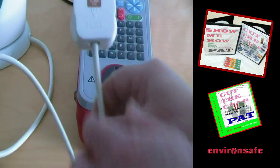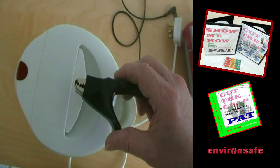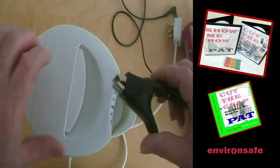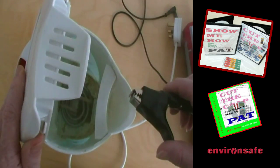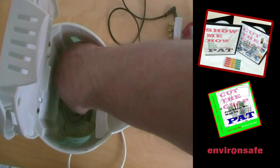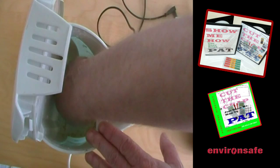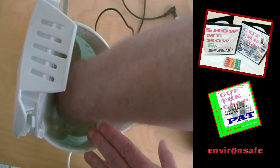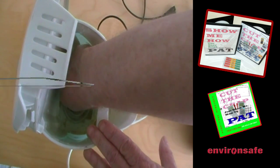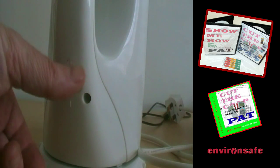Connect the appliance lead to the tester. Connect the earth bond lead to the element of the kettle. Turn on the appliance.